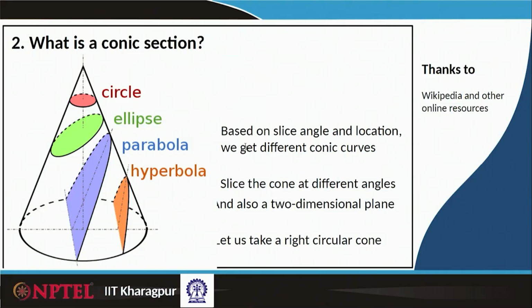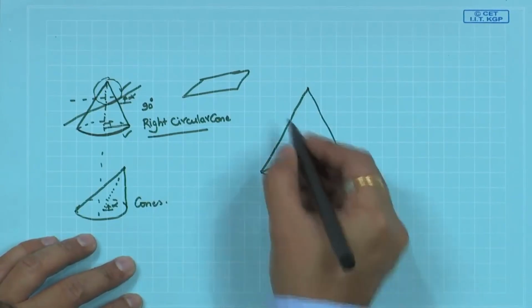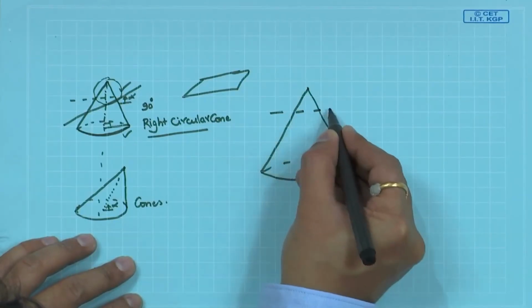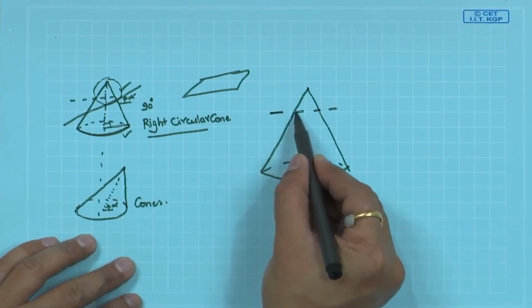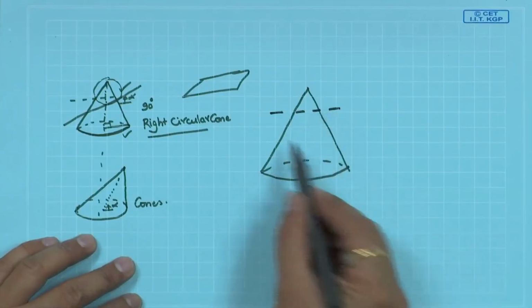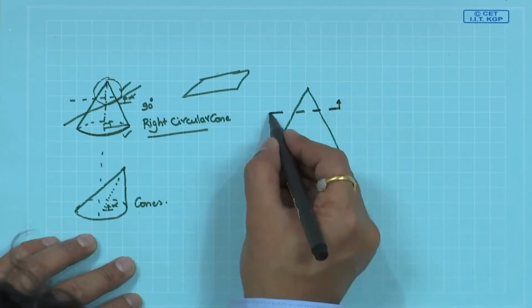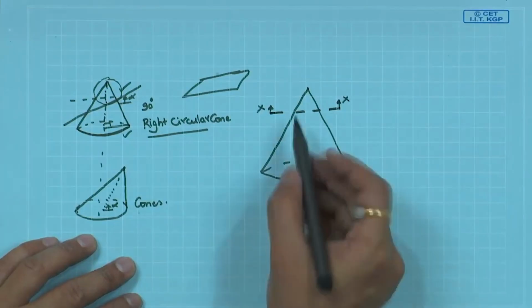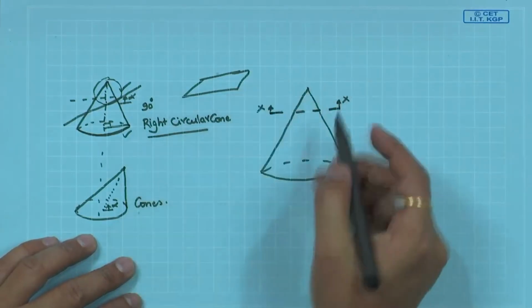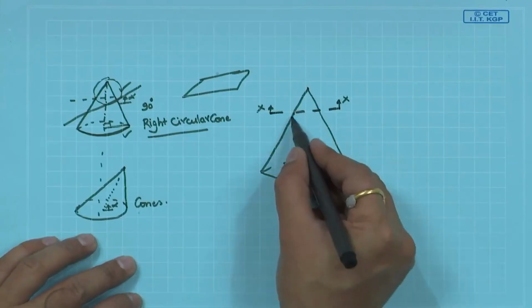For example, for the same right circular cone, if we are making a cut section, usually cut sections are shown, if we are making something like slicing, we show it by long and thick dash lines, that indicates that perhaps there might be a section. Usually at the ends we show a mark XX, that means it is a kind of plane which we are going to slice, cut the section and show that view.